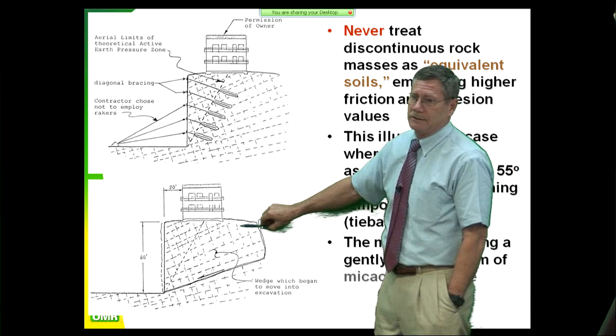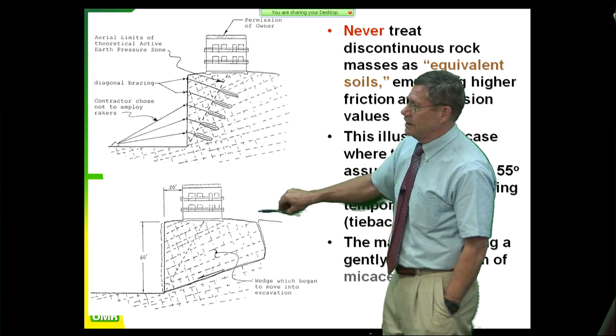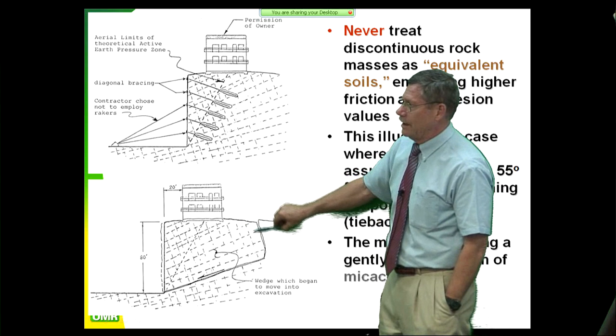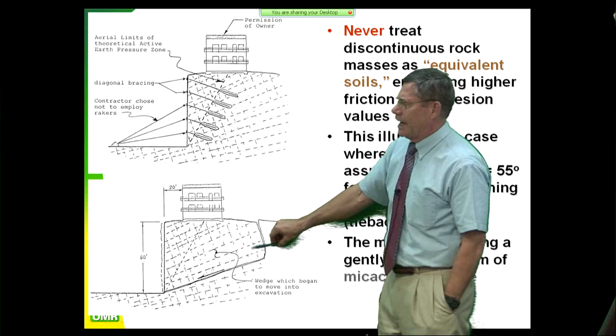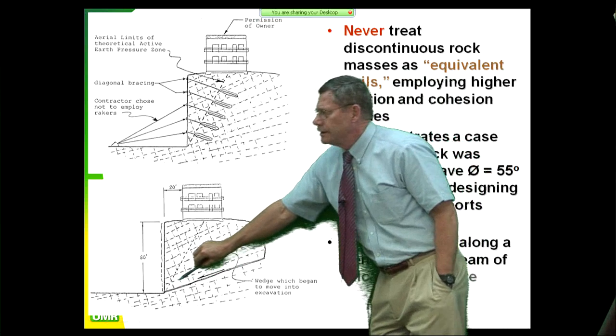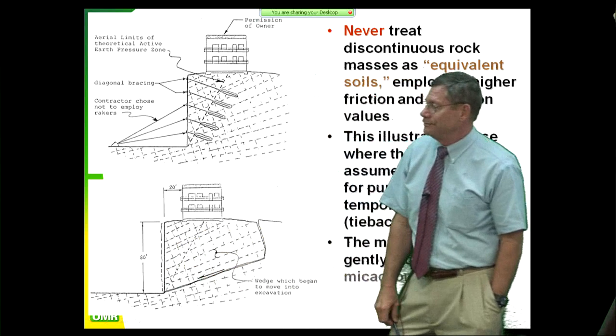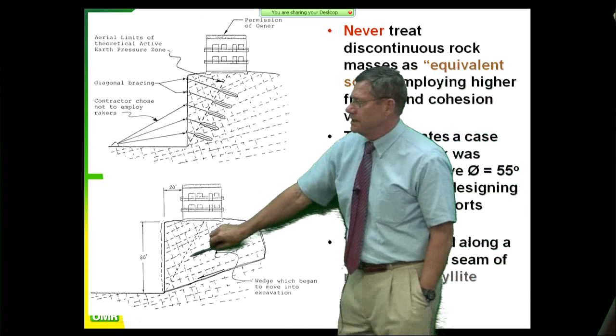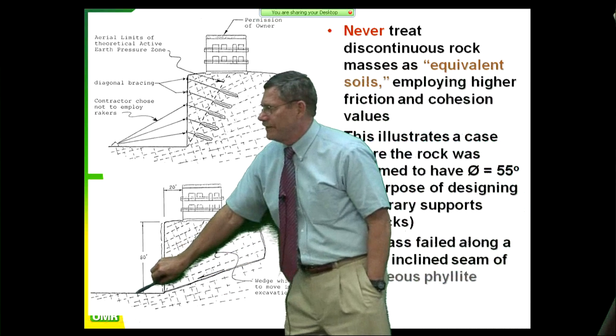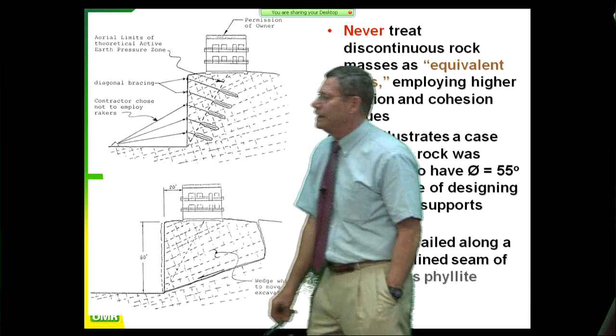If it's been a sewer line, no trouble. But this got too much water, too much head on it, 80 feet high, and the pore pressure got to a point where the whole thing just let go. And what it did here is it slid a short distance about that far and stopped. It went about 20 feet and stopped.